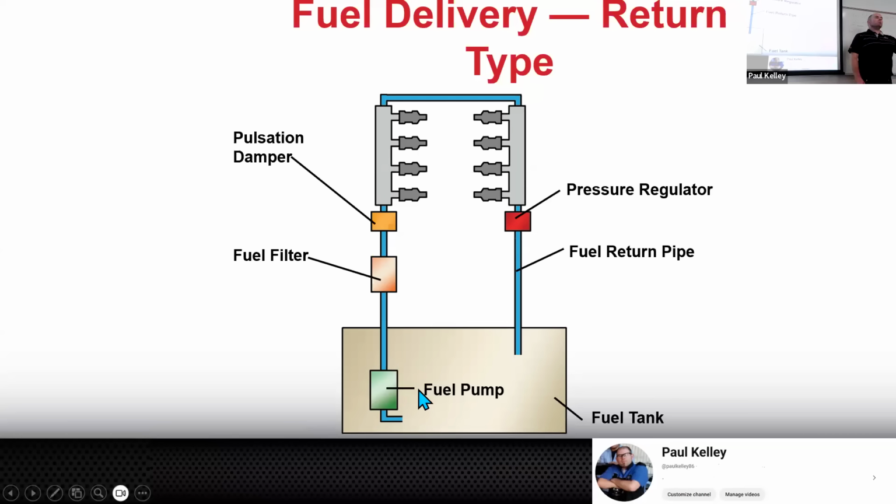The negative for you is that it's in the fuel tank. So you're like, oh, it needs a new fuel pump, what do I need to do? You may have to drain the fuel tank. You may have to take the fuel tank down. On some cars, especially a small performance rear wheel drive, because they needed a larger fuel tank but it's a small body, sometimes the fuel tank goes over top of the drive shaft. Other times the fuel tank is really long, like on a big truck. They're kind of hard to handle. Fuel tanks come in all shapes and sizes. If you have to drop the tank to do the pump, it's going to be a job, right? It is what it is. We're going to charge the customer appropriately for the job. If it was an easy job, we'll charge them less. You've got to get paid for your time.